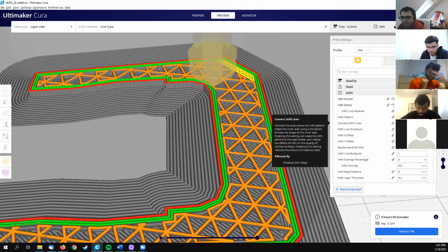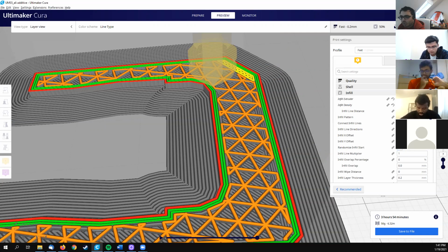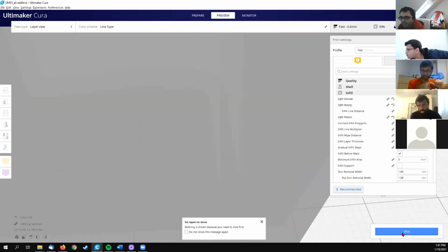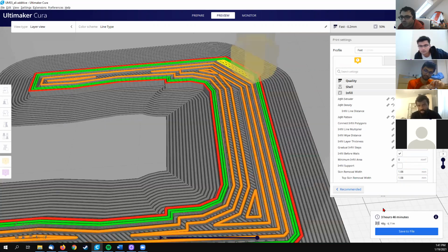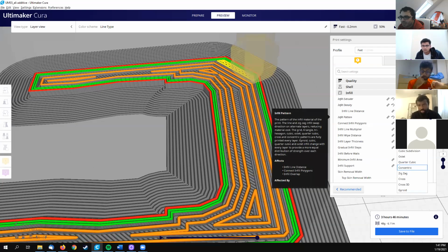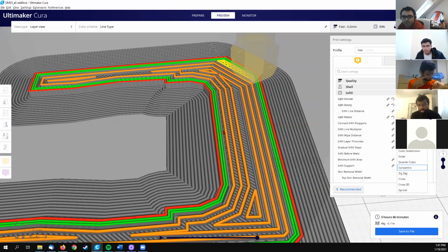Okay, and for the rest, there's a lot of small adjustments. Before I keep going forward, of course, there are different types of infills. Triangle is the default, but it's not necessarily the best. It depends on what is the function. Concentric is not so good of an infill option, as you can see. Maybe it is useful in case you have compression in the part, but it is not so well connected. You'll have internal shells inside your part, and these will not reinforce it well enough.